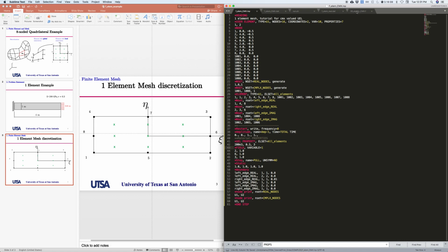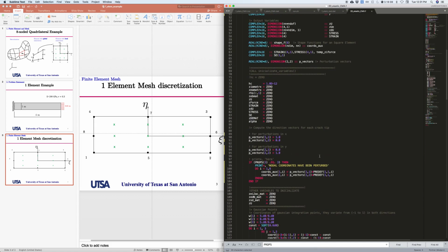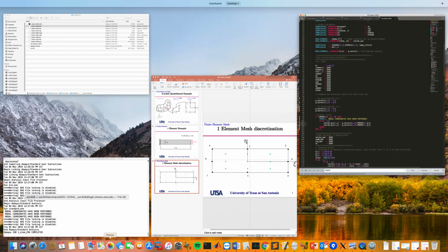And in my UEL, when I'm reading the perturbation, I'm reading it from the predefined field number 1, so nothing has to change. If you have several fields, for example if you're doing different shape perturbations and it's your field number 2, I think you have to change this one to the field variable that you have. Okay, that's a very good question.